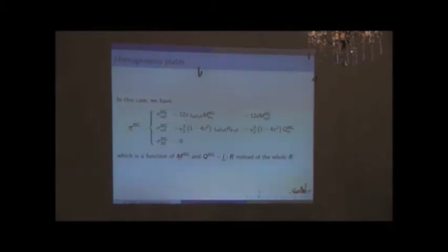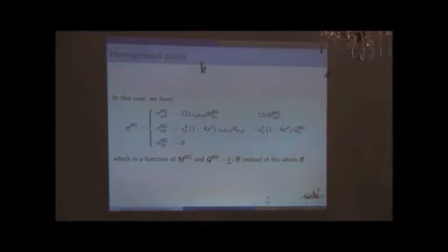So you can express it directly. You don't need to keep all the 6 components of the bending gradient, of the generalized shear force. You can keep only the 2 components of the shear force, which carries the energy related to shear.